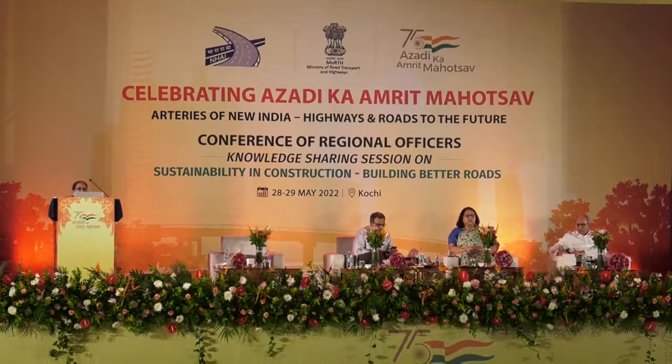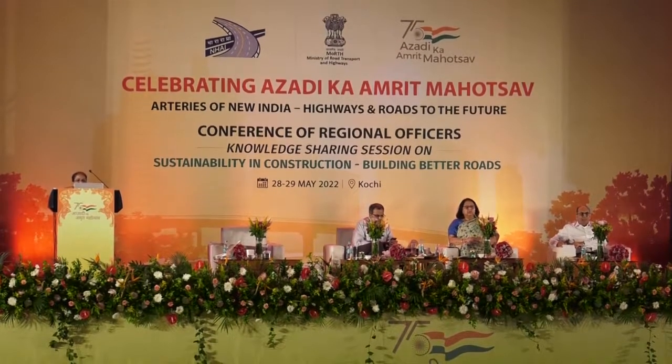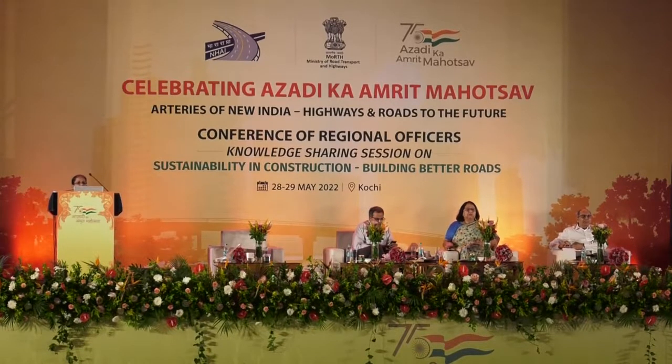To address the problems of increased traffic, tire pressure, rutting, low temperature cracking and fatigue cracking, we need modified bitumen. Especially in the Kochi area, when we talk about natural rubber modified bitumen, BPCL is the only producer of natural rubber modified bitumen, where we mix latex with the bitumen in various percentages and produce NRMB. And there are other grades of modified bitumen, which are crumb rubber modified bitumen and polymer modified bitumen.